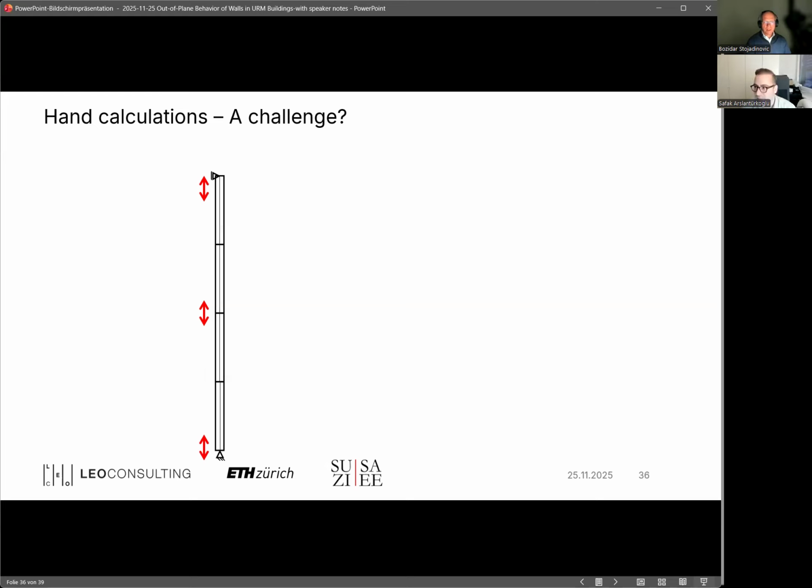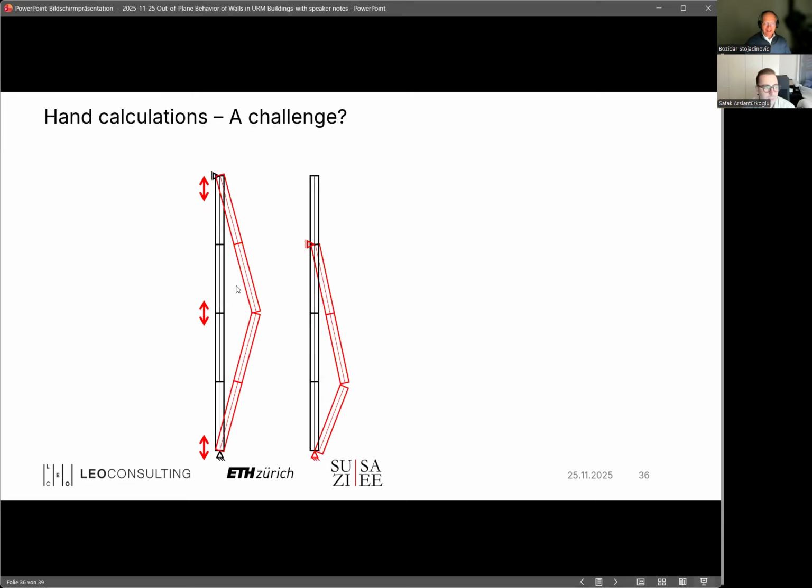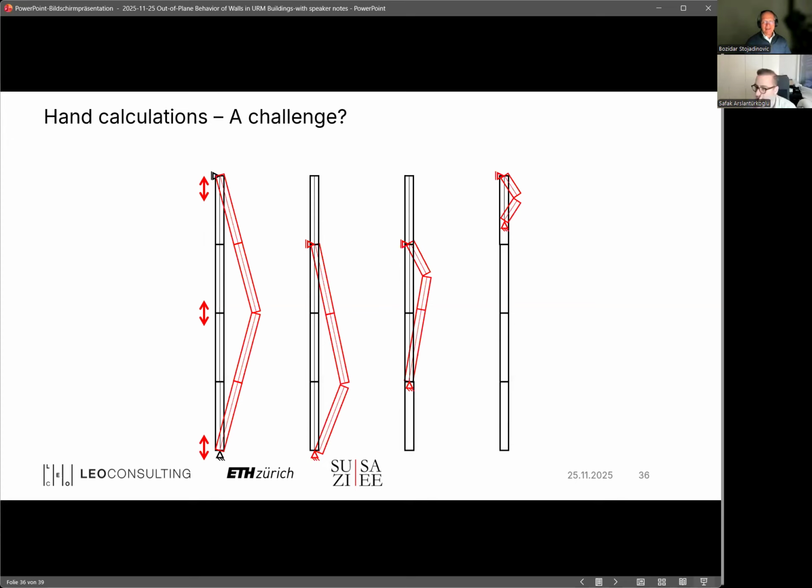Yeah. But based on earthquake experience, it's very, very common to have the top part of the building, the parapet, fall out because of the very small axial loads. And that is one of the last mechanisms you have in this figure, if you run the whole animation. That one. Yes.